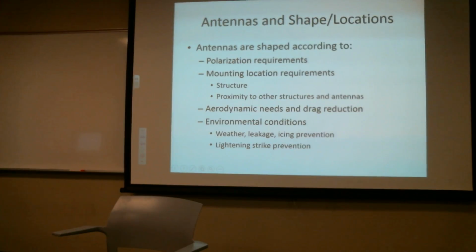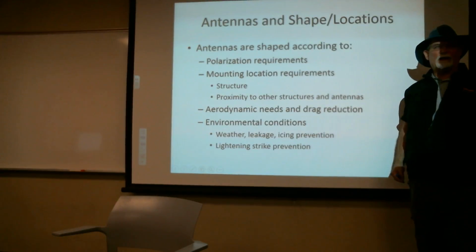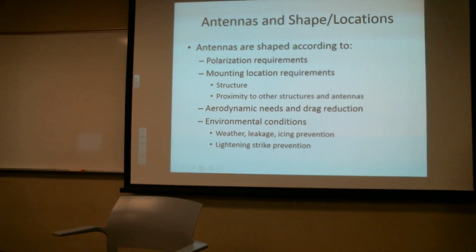Another thing that's going to be important is what are you attaching it to? If you're attaching it to planet Earth, well, just drive some spikes into the ground and hope the wind doesn't blow too much. If I'm mounting it to the airplane, you know the wind's going to blow quite a bit. Otherwise, it's not really an airplane. Okay, it's a piece of art. So at that point, I'm going to have to take into account the structure and the wind loading on that antenna. Certainly in ground-based antennas where you're trying to get altitude, wind loading can be pretty significant.